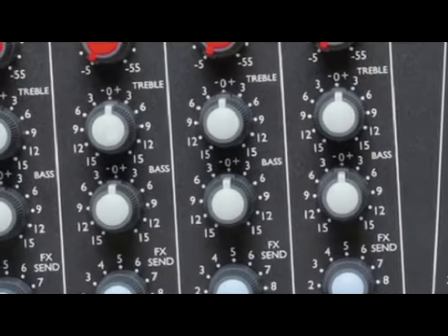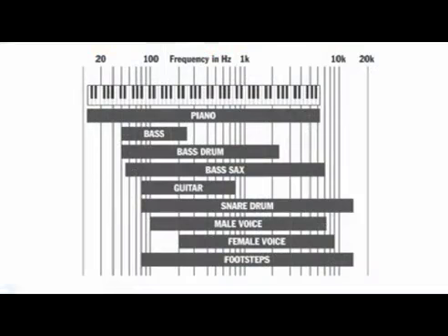There's a drawback with fixed EQ, which is that if you want to work on a particular sound, the punch of a bass drum or the ring of a cymbal for example, you won't be able to focus the EQ on the exact frequency. In fact, you can only boost or cut a pretty huge part of the audio spectrum, and you'll end up changing much more of the sound than you might want to. On the other hand, if you just want to add a little warmth or sparkle to a sound, then as little as a quarter of a turn of the knob should do the trick, especially with low frequencies like bass guitars and bass drums. You can keep yourself out of trouble if you remember, always cut rather than boost where possible.